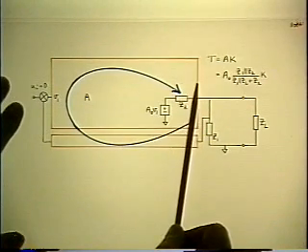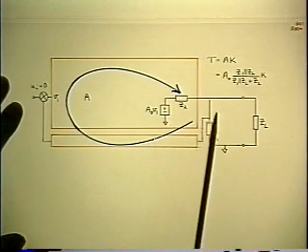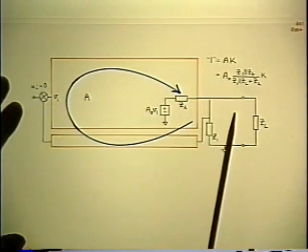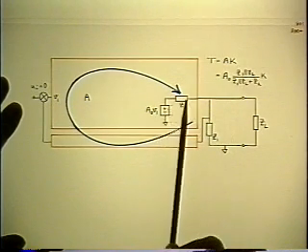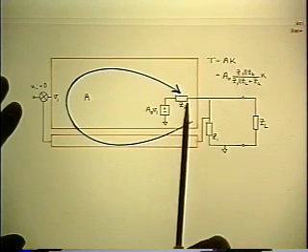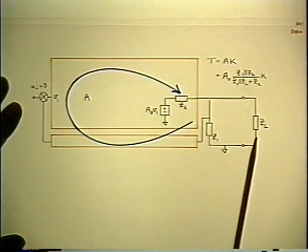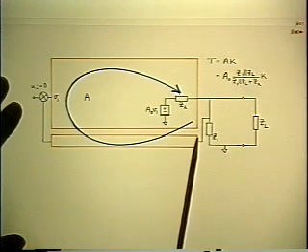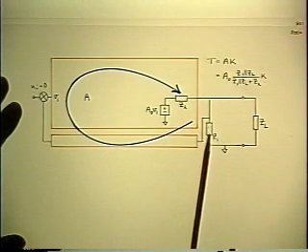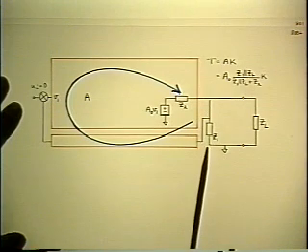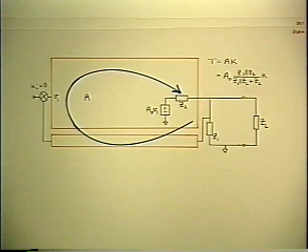Here's the single loop feedback system where the boxes have been expanded so I can get a little more inside them, and also a little more specific to do with the connections of the system at the output. So the output of the forward path is represented by the Thevenin equivalent of a generator and a series impedance Z2 feeding into an external load. Connected across the output also is the feedback path, and it usually has a non-infinite input impedance, which is represented by the Z1 in this box, or there's some other impedance there across which the feedback is developed.